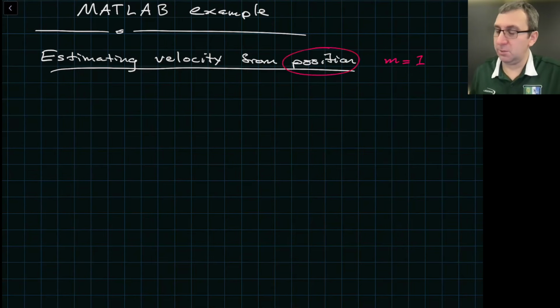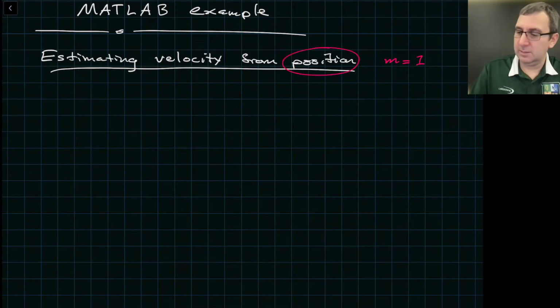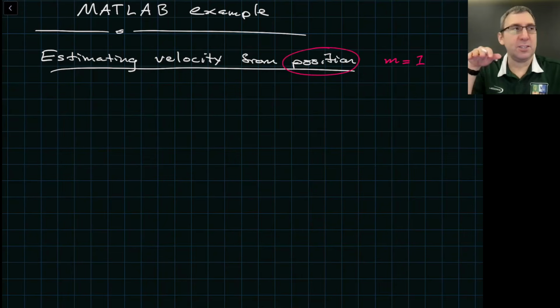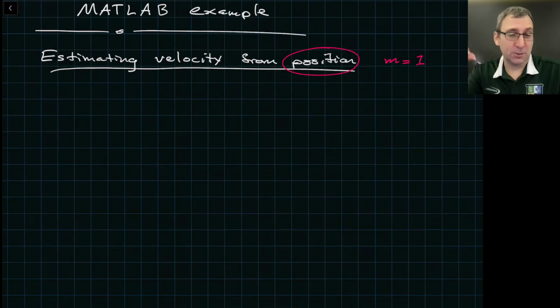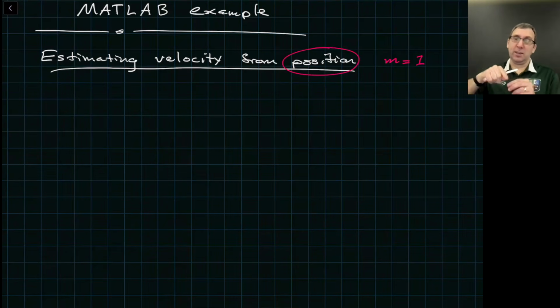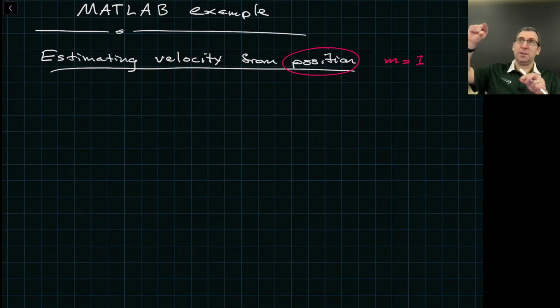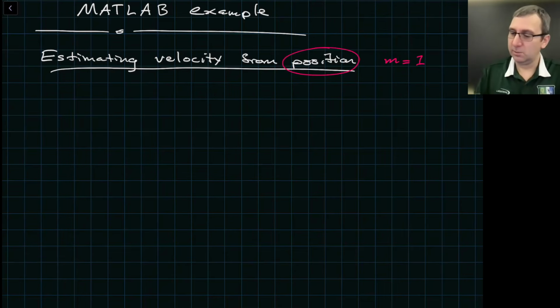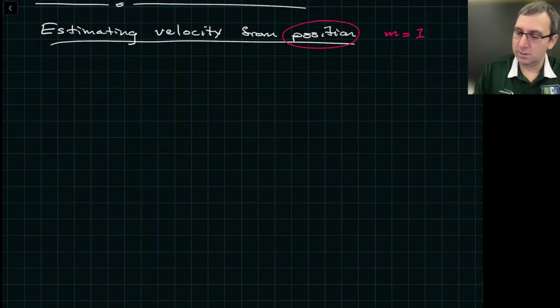We're just getting position. We could apply this to something like that sonar altitude data, so that not only are we getting a more precise estimate of the altitude, but we actually get an estimate of the velocity. And how can we do that? It's because position and velocity are related through a linear state model. Let me show you how that works.